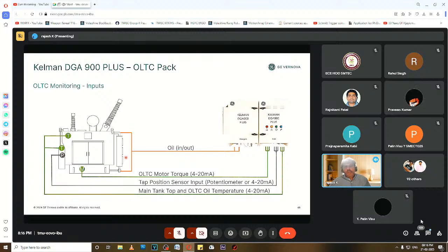And then we have the OLTC based. So OLTC, as you know, we monitor and change the taps based on the loads. Okay, so based on the voltage, we change the taps, which is usually on the high voltage side. So based on the voltage, based on the loads, the voltage changes, and of course you can change the tap, and it is prone to failure as I was mentioning earlier. So we can always have a sensor to see the tap position and compare with the parallel transformers.